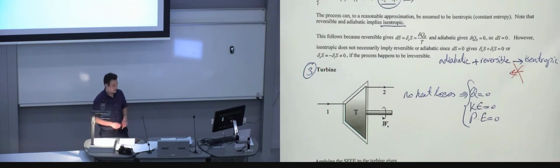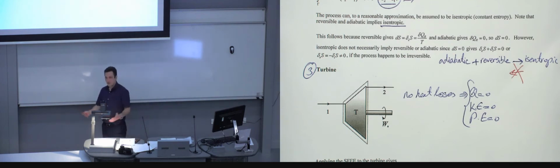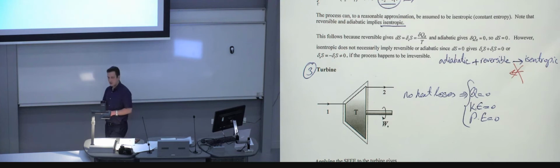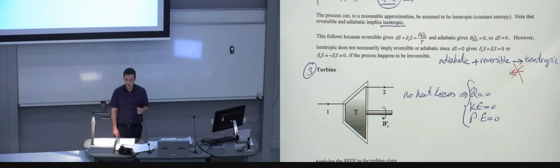These two are common and it sort of makes sense, but the first one, which is the no heat losses, you might think, and I think I have mentioned this as well, that a turbine certainly is a very hot component. Obviously it has to be quite hot. It's operating at high temperature. Therefore, how can you ignore the fact that there is some sort of heat loss there? If you have a perfectly insulated casing for a turbine, then you can assume that regardless of the temperature, you're not going to have any heat losses from the turbine itself. So the fact that a device or a system is operating at 500 Celsius, 600 Celsius, whatever, doesn't mean that it can't be adiabatic. It can, if you assume that you have perfect insulation. And in this case, that's the assumption we're going to make.